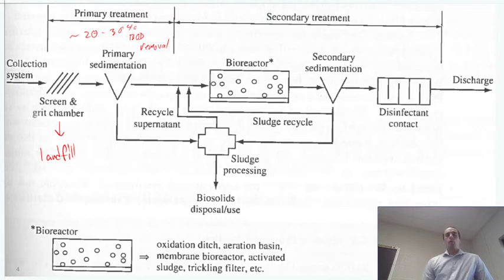And then we will also take whatever sludge we collect here and send that to sludge processing. We're going to add to that the secondary sedimentation, which happens after we grow a bunch of biologicals, right? We're going to keep a bunch of happy bacteria growing. Sometimes we'll use cyanobacteria, as is the case we saw a few minutes ago, that lime green wastewater discharge. Essentially, that's going to be some algae and/or cyanobacteria. So there's a technical difference there.